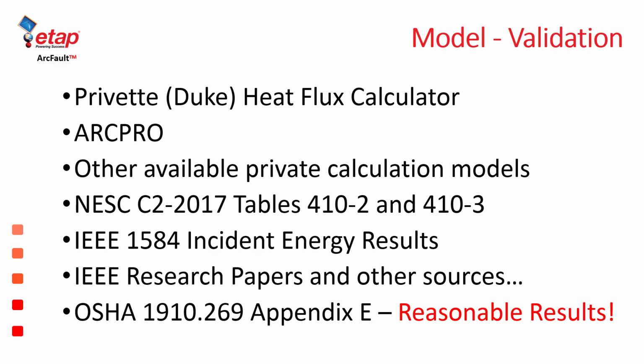Of course, ETAP ArcFault is not a table method or derived approach. It is a full calculator of the arc physical behavior, including the heat flux at a certain distance from the point of the arc fault. We also use IEEE 1584 incident energy results to validate some conditions for open air three-phase fault arcs, and we use countless IEEE research papers and other sources.